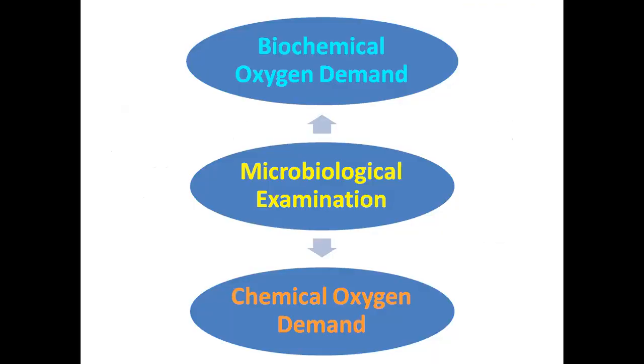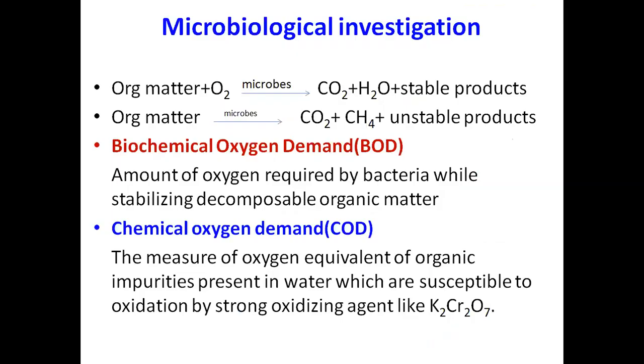Then biological oxygen demand and chemical oxygen demand. Let's see the microbiological investigation, or BOD and COD. Now remember, highly pure water will have very less BOD. Very simple logic to remember. And highly impure or more polluted water will have very high BOD. This is a very simple explanation: pure water will have very less BOD, impure water will have very high BOD.